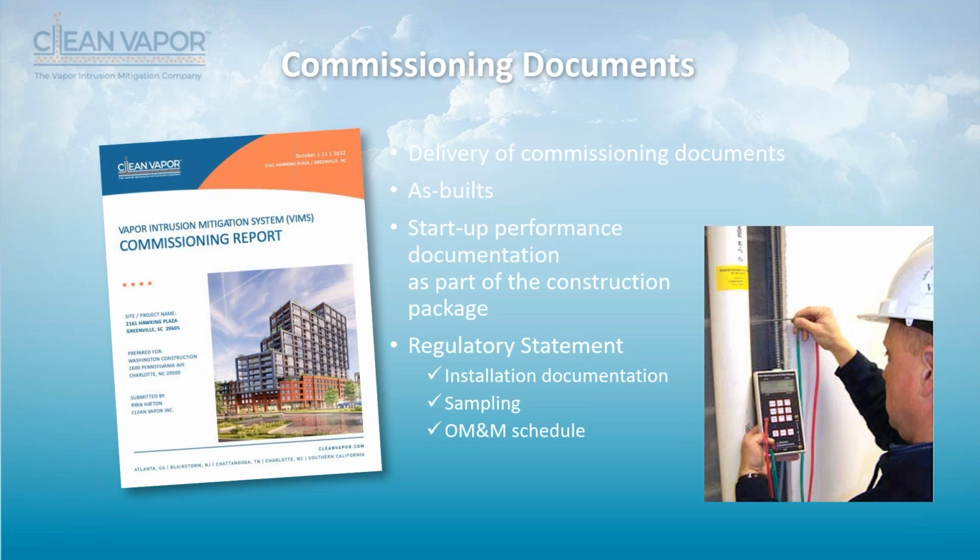We just went to activate a building up in the Midwest. It had a system on it. We put a fan on it. The fan was maxed out, no airflow. We can't measure vacuum 14 feet from the suction point. There's a problem. We don't know where any of the pipes are. Don't get caught in that trick bag. It's something you want to do correctly.